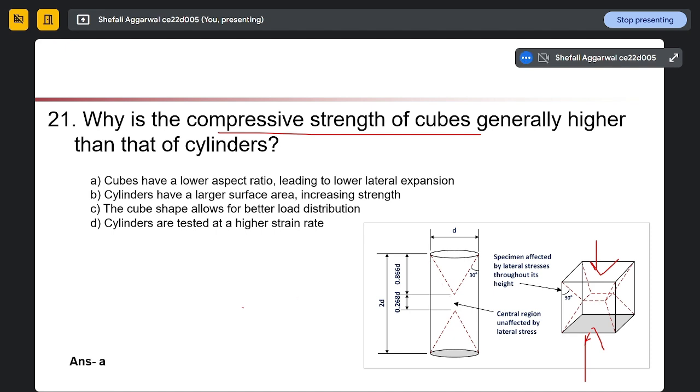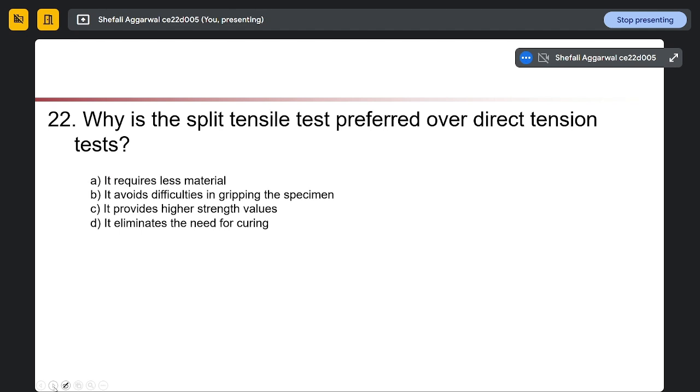So what will happen? The strength of our concrete will increase, because if we are reducing water demand, less water will be there. However, the cement content will be equal, and more hydration products, C-S-H, will form, resulting in higher strength of the concrete.